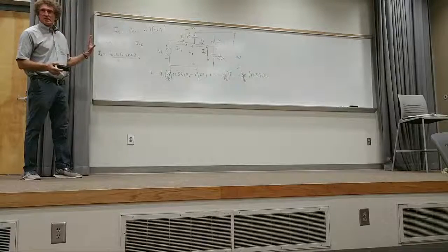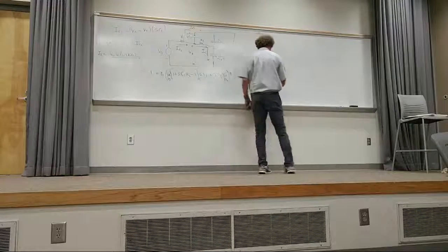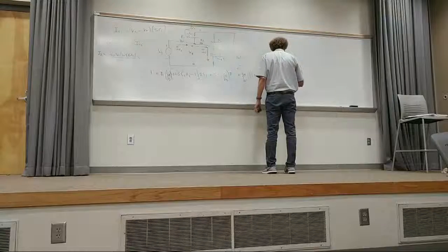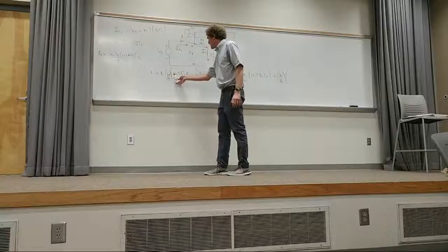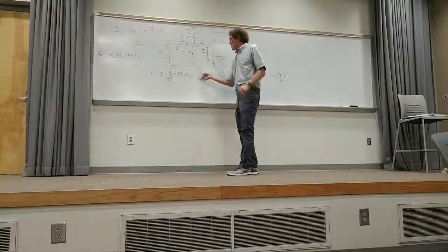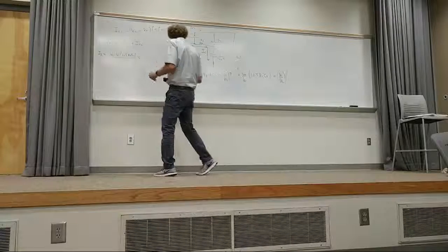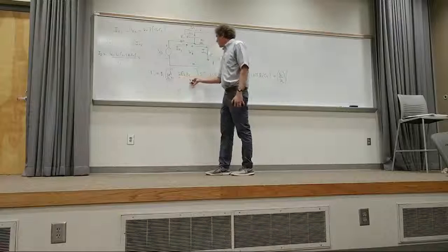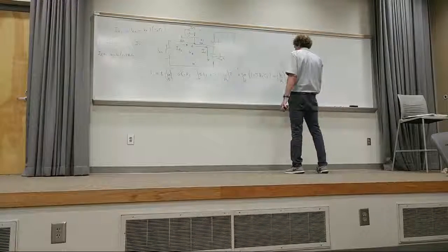Now, if you look at this, just look at the coefficients of V out over Vs, and I'll put it over here. When I take a look at V out over Vs, which is my transfer function, right here, I have R1 times this, right? But 1 minus 1 is 0, right? So I can get rid of that. Y'all agree with that? So really, I have R1, R2, C2S as the coefficient there.